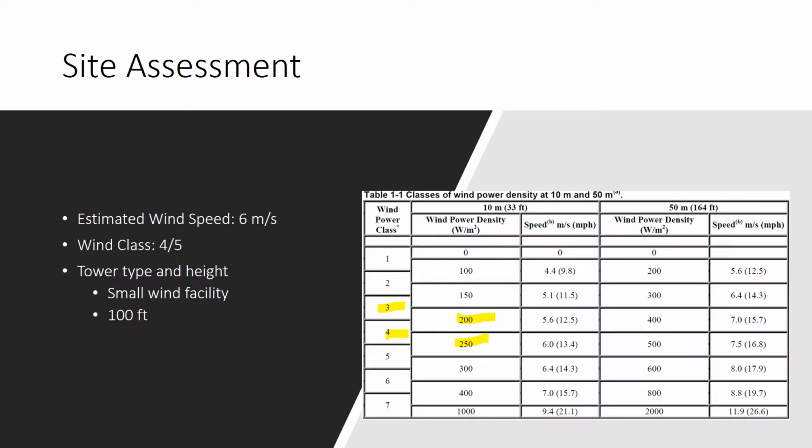Since our property is a 5-acre industrial site, the county ordinance allows us to place a wind turbine at a max height of 250 feet. From this, we can easily insert two 100-foot towers, since it would still be following the local county ordinance.